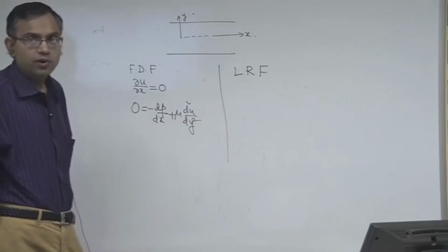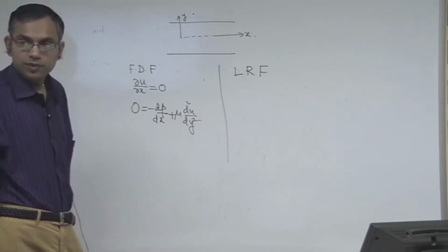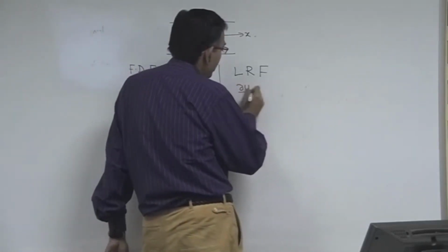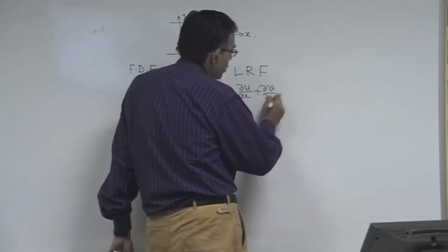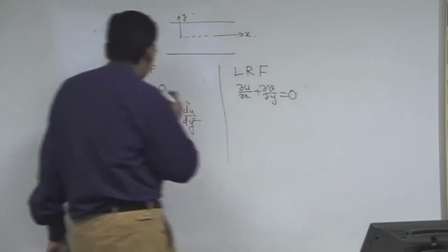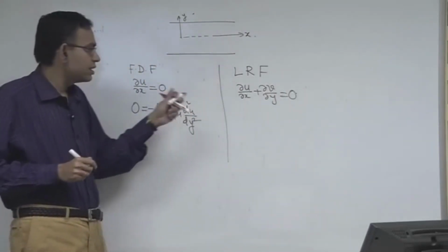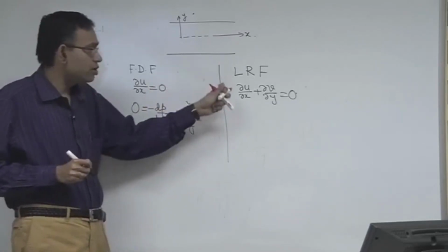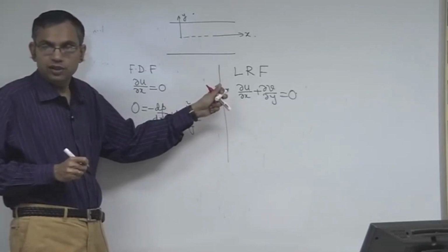Low Reynolds number flow does not require del u del x equal to 0, right. So, for low Reynolds number you will still have del u del x plus del v del y equal to 0. So, in fully developed flow if there are no holes in the walls, then that will mean V equal to 0 identically, but low Reynolds number flow does not require V to be identically equal to 0, right.